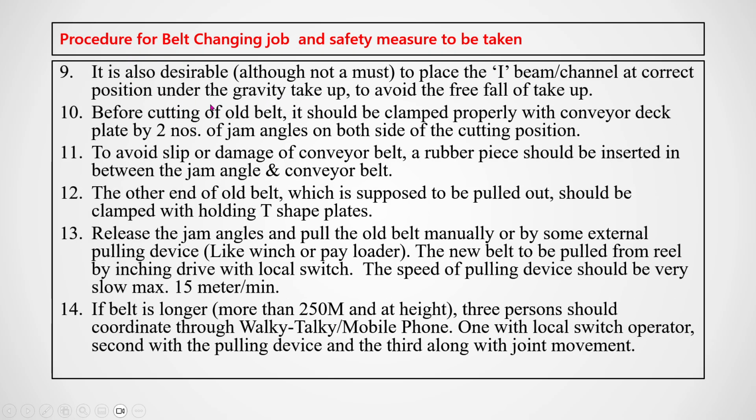Then it is also desirable to place an I-beam channel at the correct position under the gravity take-up to avoid free fall. If you are using a gravity channel, then you have to place it in the proper location so that all the gravity load should not fall down. Before cutting the old belt, it should be clamped properly with the conveyor deck system.